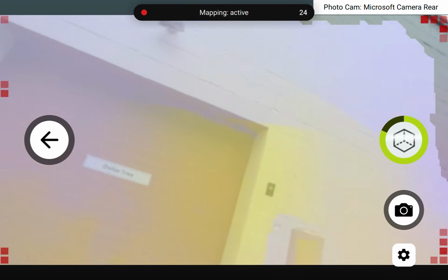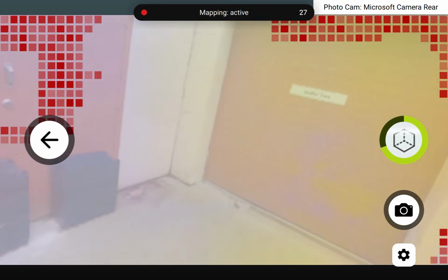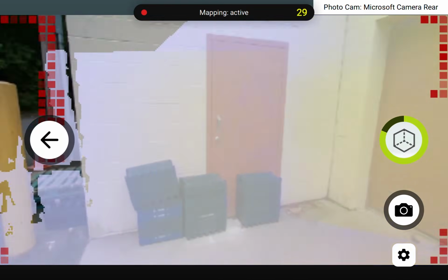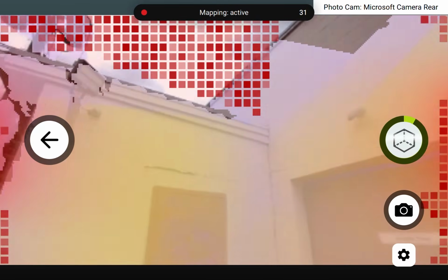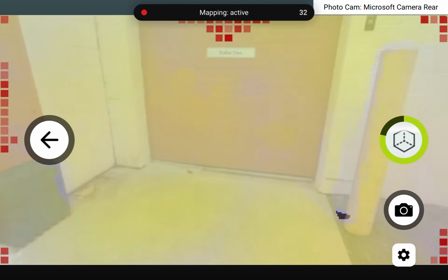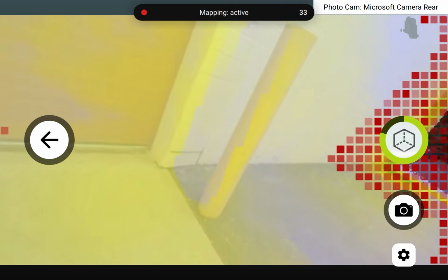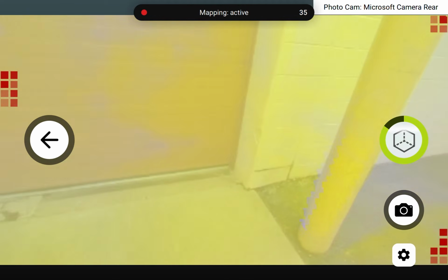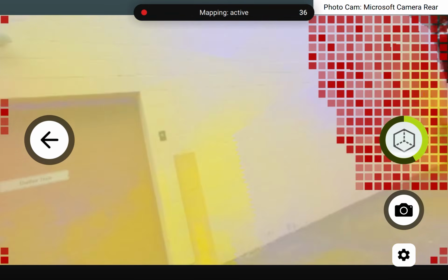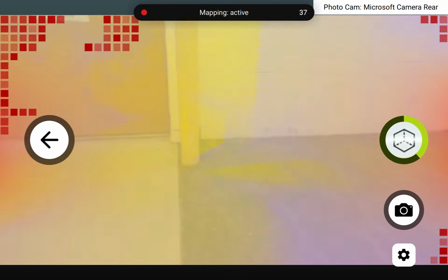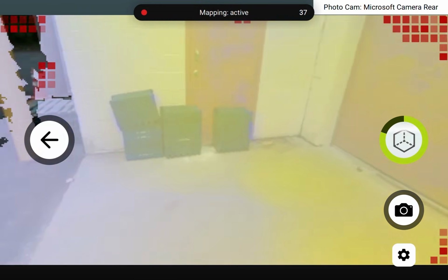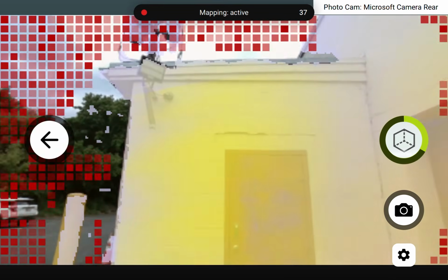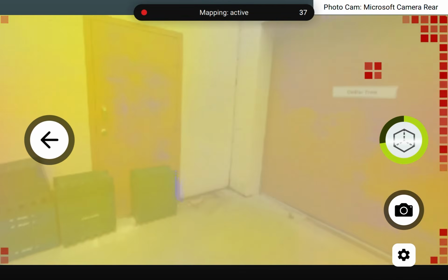You'll also notice that you see these red squares showing areas that are not currently being captured by the camera. So on your far end of the spectrum, that would be a 14-foot maximum range, or on the close end, a 1-foot minimum range. Although you generally want to try and keep your device in the sweet spot of about 4 to 8 feet from the target, generally capturing from a little further back to start and then moving in closer to get more detail as needed.